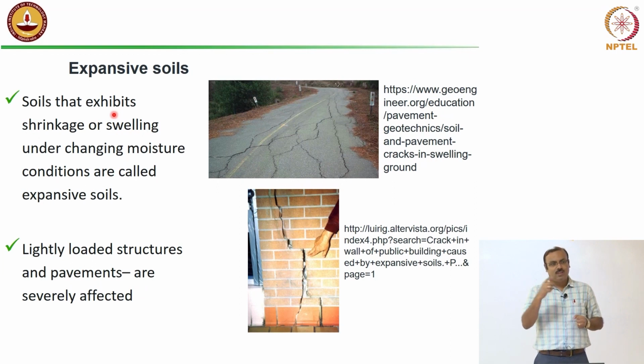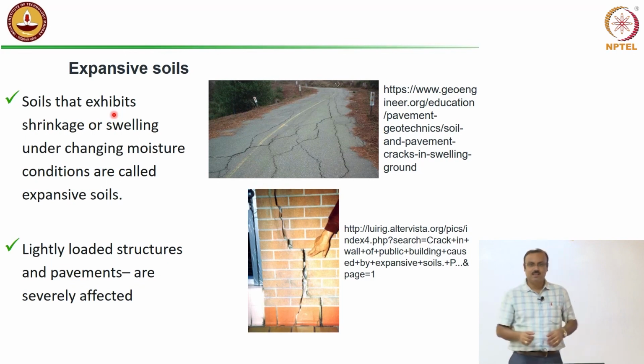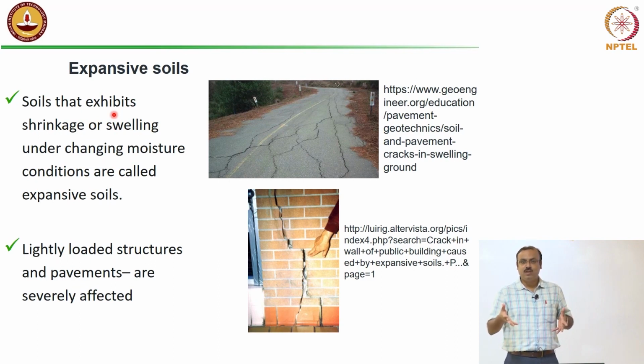That is fine. Now, next time monsoon is over, it's bright sunshine, dry season, what will happen? They will expel the water very fast. Now, while expelling the water, the volume of the soil will reduce, right? It's a kind of shrink, it will shrink to a small volume. Now, consider a structure standing like this, with soil below doing this kind of thing. In rainy season it is absorbing water, increasing the volume, and in the dry season it is expelling the water and shrinking. What will happen?